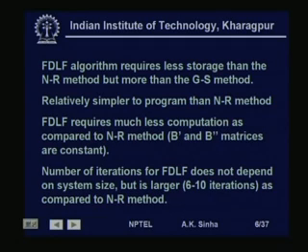Whereas, in case of Newton-Raphson method, you have to compute the Jacobian matrix in each iteration and then factorize it in every iteration for finding out the updates for voltage magnitude and phase angles. Whereas, in case of fast decoupled, we do not have such a situation, since B dash and B double dash matrices are constant, they can be factored and stored once for all the iterations.